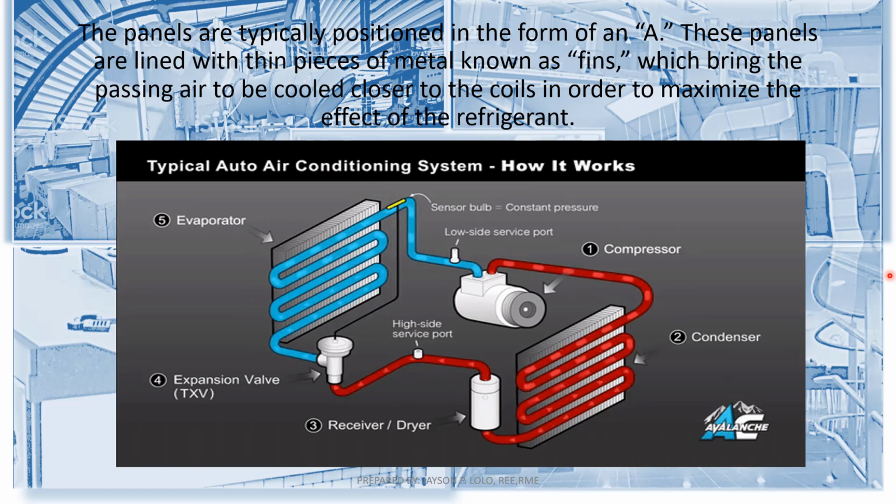As the air conditioner runs, the compressor pulls cold, low pressure liquid refrigerant through the tubing in the evaporator coil. The refrigerant passes through the expansion valve here. This valve relieves pressure from the liquid refrigerant, which rapidly cools it.